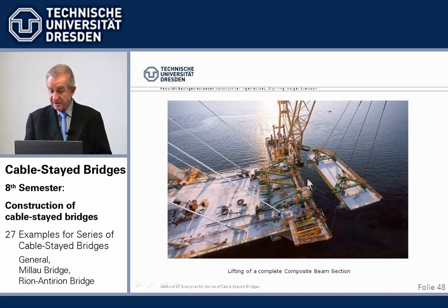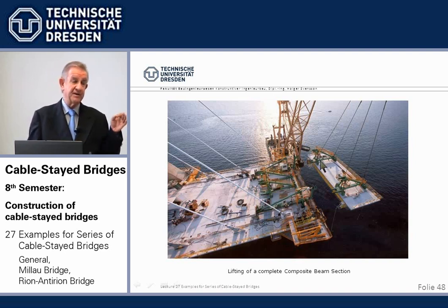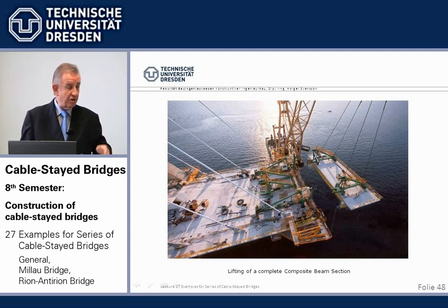It helps a little bit with construction time, but of course I lose the big advantage of having to lift only, say, a 60-ton steel grid and the concrete in pieces, or this weighs about 270 tons. But apparently they had this huge floating crane on site, and that thing didn't mind whether it's 60 or 270 tons to lift. And so this was then easier to do.